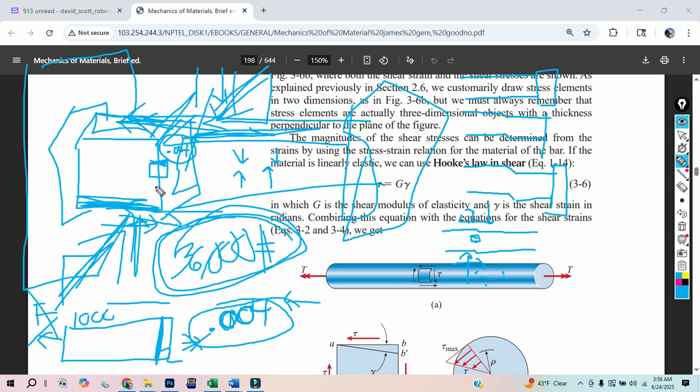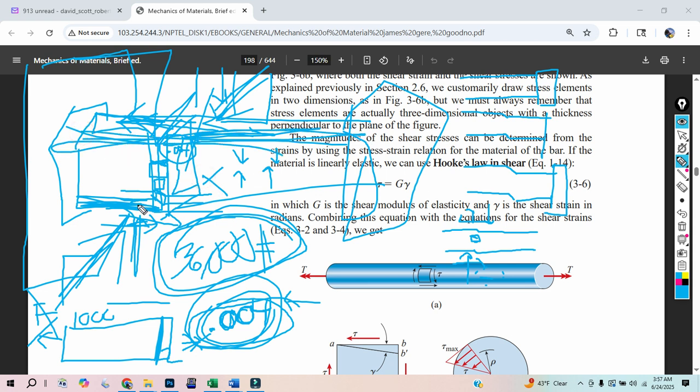And so when we do that, I at least have a few molecules that are square and then can bend at that angle, even if every other molecule's right and left are bound by the vise or the device that's holding them square. You know what I mean? That's fair enough. But along that shear, you are going to get elements that are going to turn into a diamond shape. A square turns into a diamond, but if you're not at that 0.004 limit or past, you can let go of the force and every molecule goes back totally straight.